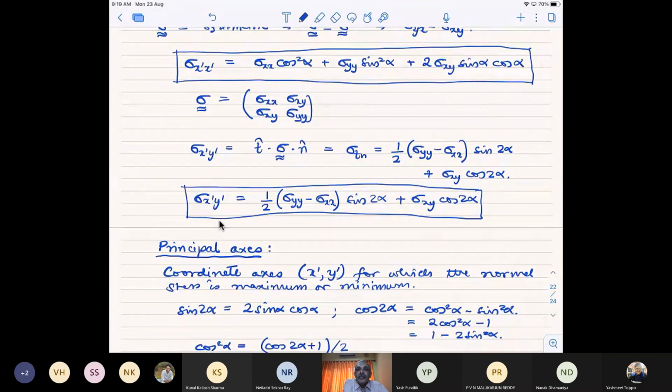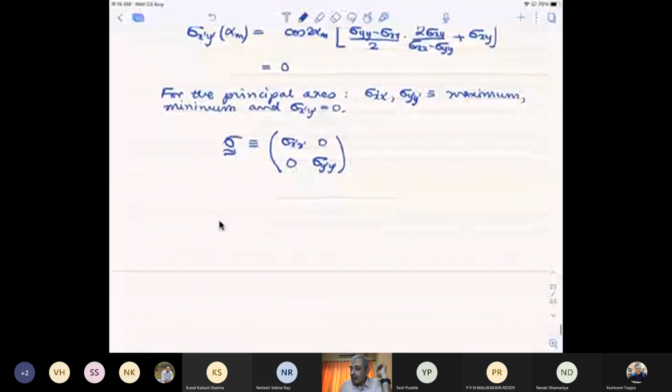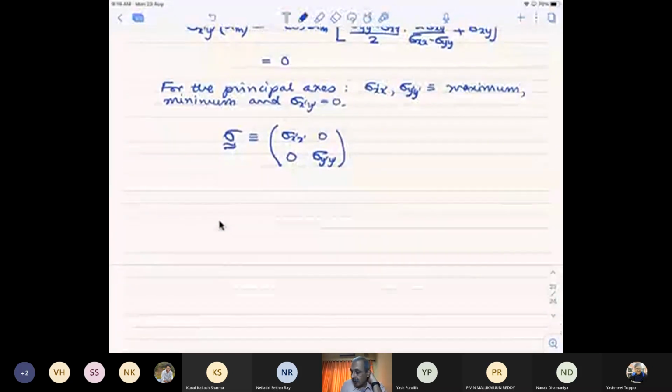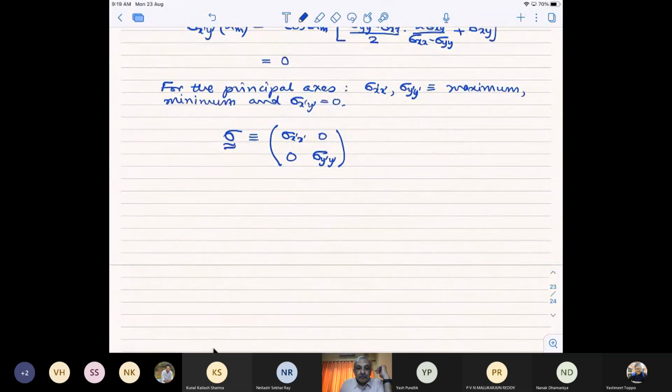The ratio of those two is a constant. Similarly, when you have a continuum, we will see that at the point of yield, when the material just starts yielding, the ratio of the shear stress to the normal stress becomes equal to the yield stress. But it's not just any shear stress or yield stress; it's at a very particular value.